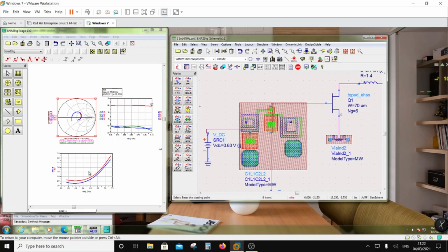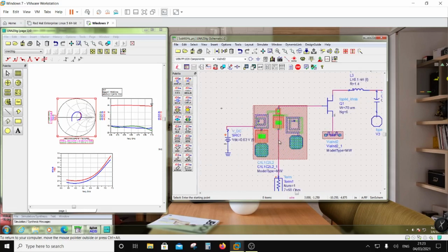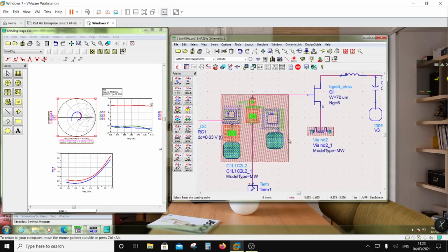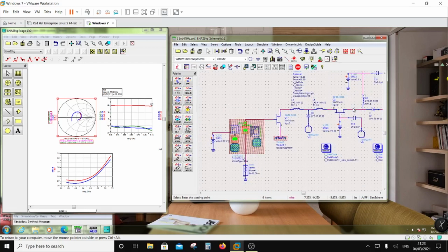Now, how much improvement can you do on the loss, right? Well, it seems like this is a 1.3 dB loss. And if you can bring it down by, say, 0.4 dB, your noise figure will go down by 0.4 dB. So basically all the struggle over here for a designer is going to be minimizing the loss of the input stage. But here I am not going to optimize that, because I know that this is a very lengthy process. So rather I will proceed with the flow.